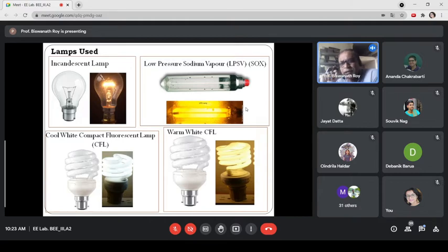In this electric lamp, this discharge tube, we are getting golden yellow color where electrical energy is supplied. So electrical energy is converted directly to golden yellow light. This is electroluminescence. So this is luminescence, but electroluminescence because the input power is electrical power. This is the case for the low pressure sodium vapor lamp.